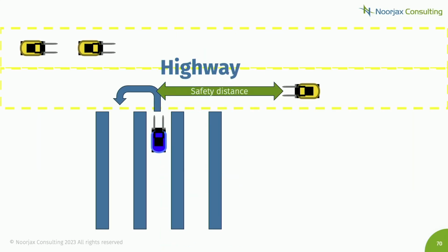So let's see what the characteristics of the movements are, which are pretty strict. The client was very strict in terms of how the movements were seen in the simulation. One thing is that you need a safety distance for a truck to be able to make a U-turn from one aisle to the other aisle. And this safety distance is a parameter.